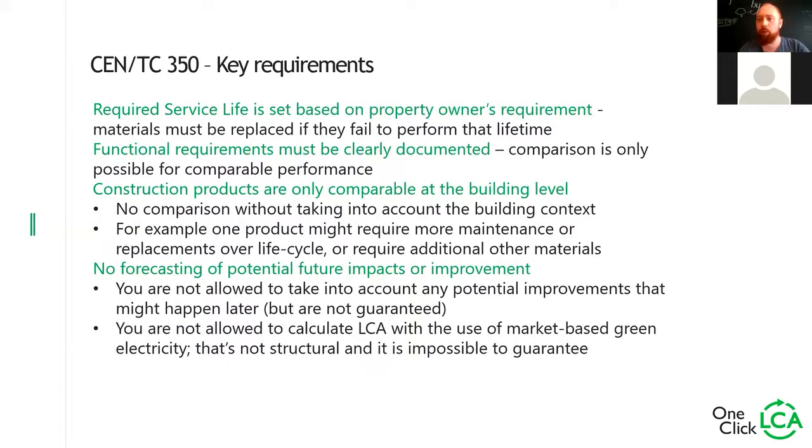There are some requirements for doing your LCA. So we have to set a service life. So what kind of period are we looking at for a calculation? Any materials that don't meet the service life will have to be replaced or refurbished. So if we have an office building of 60 years, and we have some doors that we buy, and our manufacturer tells us this door will last 30 years, they will have to be replaced at year 30. So there will be some material emissions for the replacement.